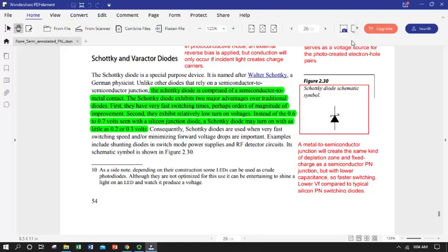The capacitance is much, much lower, so it can switch quicker. If we reverse quickly the direction of current, like with a square wave imposed periodic signal, it's going to respond faster. It has a lower capacitance, so these are used for very, very fast switching applications. And in case you wondered, we've got to metallize the back of every piece of doped semiconducting material that we make a device out of.